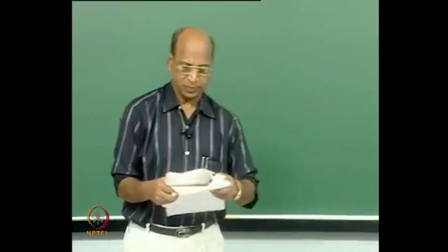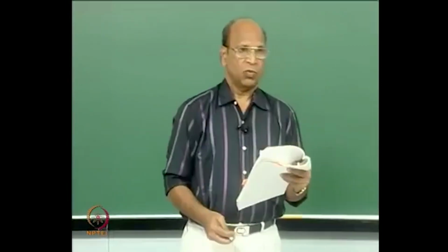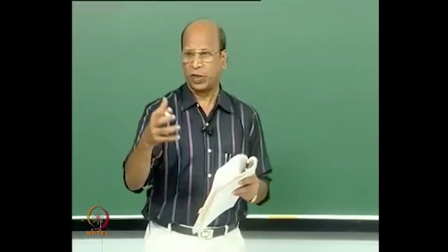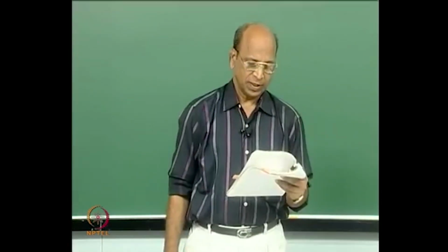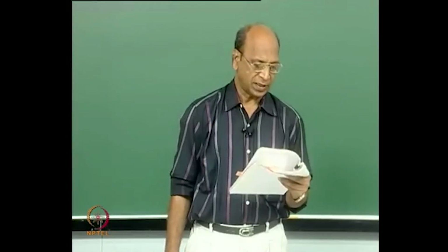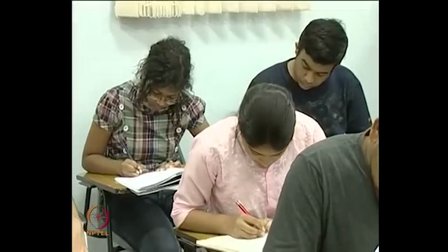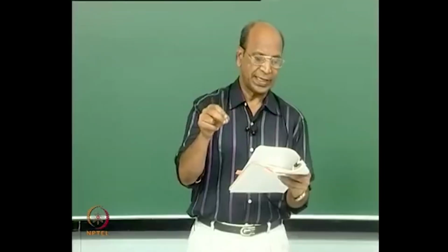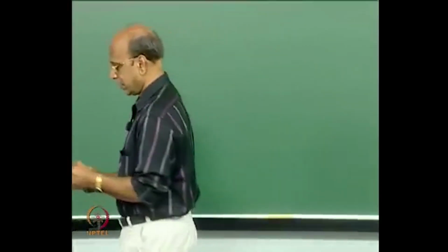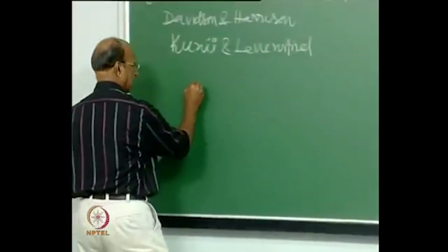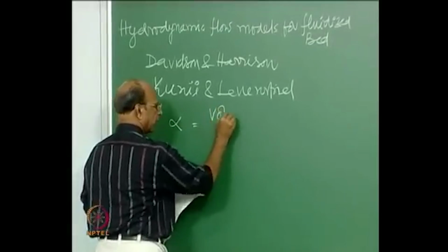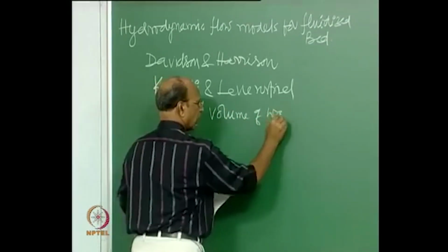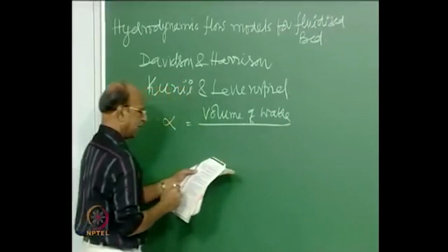The second finding, first one was the model development for the bubble itself. The second finding on single bubbles is that every rising gas bubble drags behind it a wake of solids, defined as alpha equal to volume of wake divided by volume of bubble.